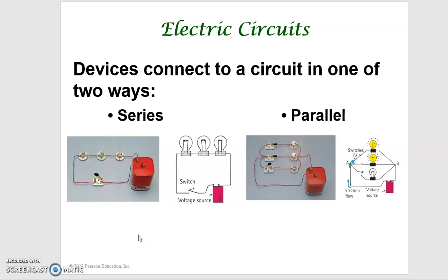So the three resistors in series is the concept of the series circuit. You may think it is very trivial, but I will give you more physics later. And how about the parallel circuit? The current comes out from one end of the battery and flows into the three resistors. You can see that each of the resistors has its own switch. The current passes through each of them, and the current is combined together at this point and goes back to the other end of the battery.